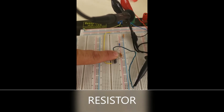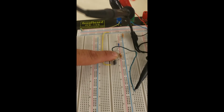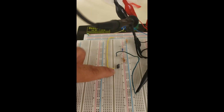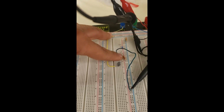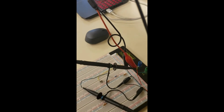It's approximately 0.995 kilo ohms. And then this is our 0.22 microfarad capacitor. We're checking the output from ground to the junction between the two resistor networks. Our blue probe here is viewing our output on our oscilloscope. Our green probe here is viewing our input from the function generator.